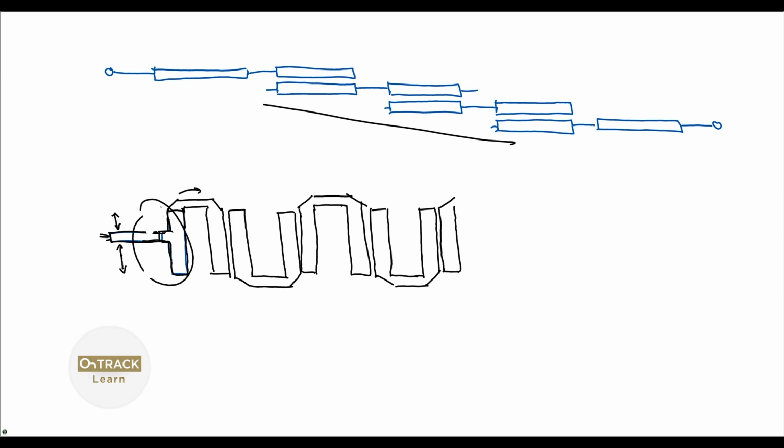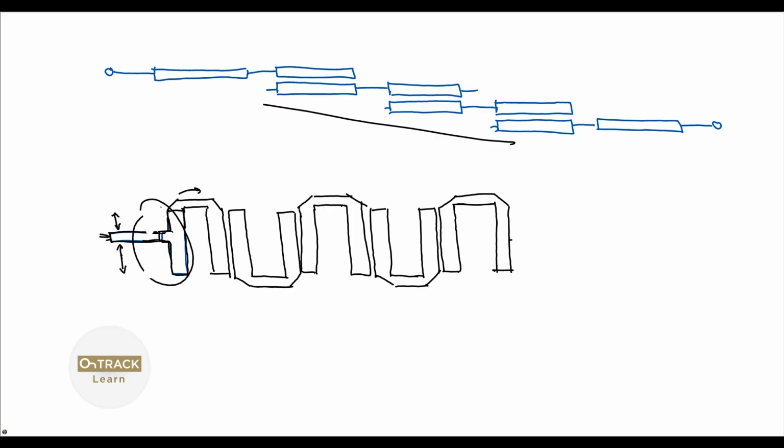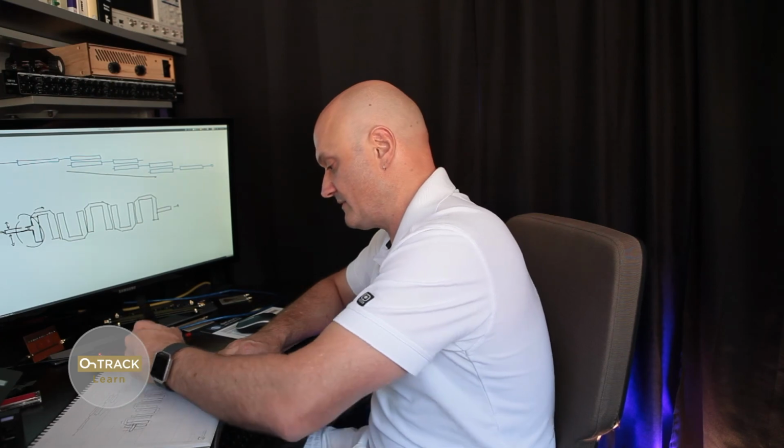And we do more segments if we want steeper side lobes or steeper walls on our filter. If we want a steeper frequency response, like more of a brick wall, you add more segments. Like any passive filter, you add more inductance. If you want a steeper walled low pass filter, you add more series inductance, more parallel capacitance at the corner frequency that you want. And then at some point you've got enough, and this carries on as the output to the filter.